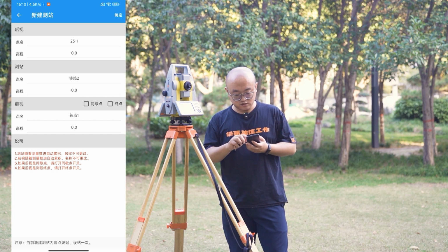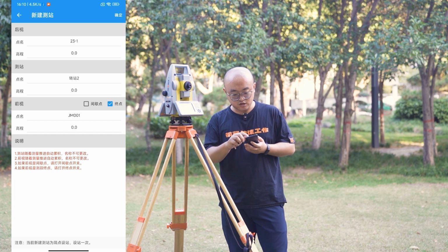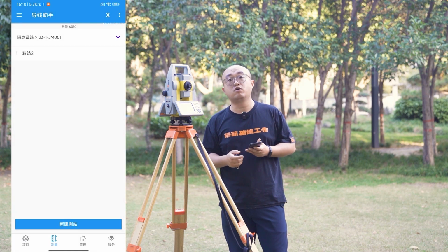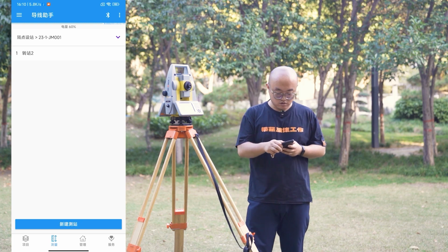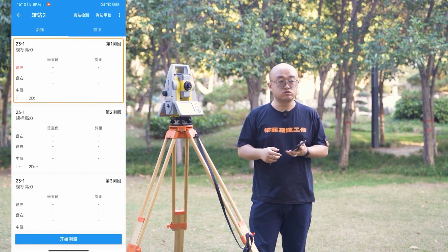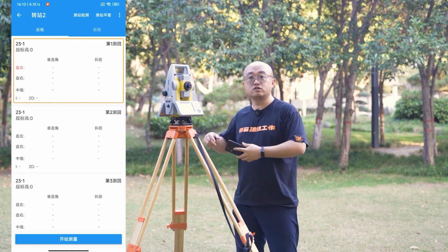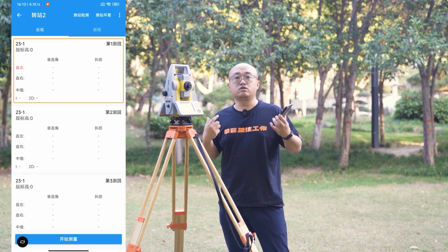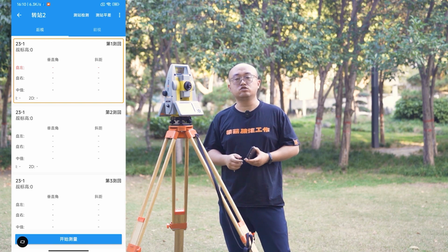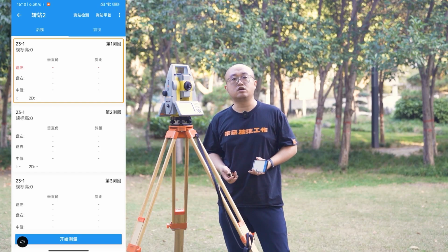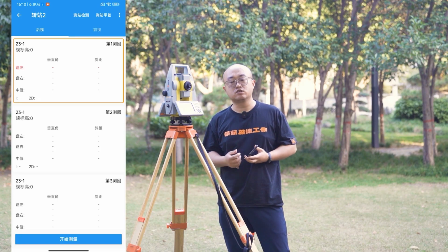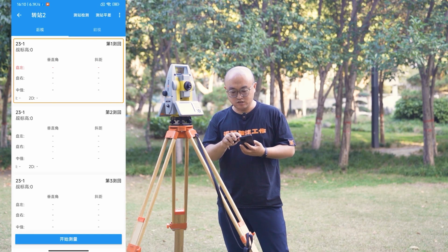If you can observe them, you can directly select the endpoint, go from 23:1 to the endpoint of the route, and then click OK. In this way, once the measurement station is created, we can directly enter the measurement interface. Observe the backward target here, and then observe the forward target, which means the oblique distance and vertical angle of the two targets. Let's start observing the trigonometric elevation.